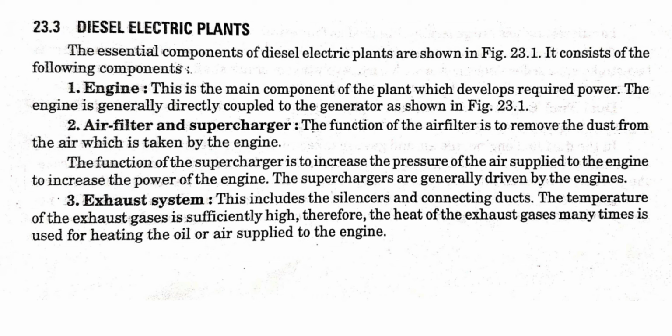Next point is air filter and supercharger. The function of the air filter is to remove the dust from the air which is taken by the engine. The function of the supercharger is to increase the pressure of the air supplied to the engine to increase the power of the engine. The superchargers are generally driven by the engine.